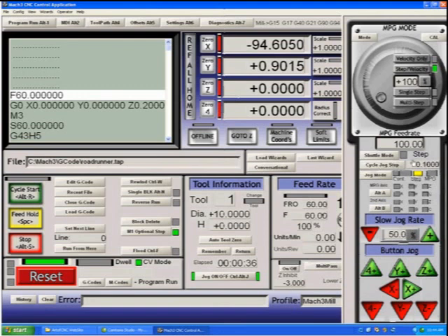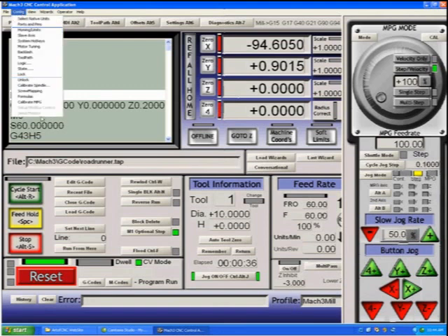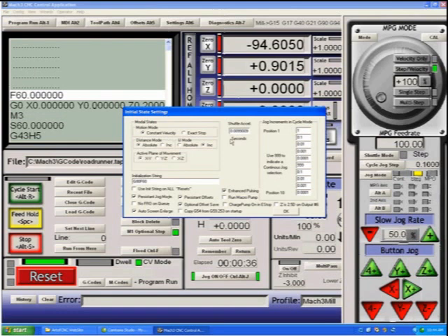And you can set these cycle jog steps in the configure state menu. Here are the ones that we are cycling through when we press this cycle jog step button. You'll see an entry here, 999. 999 triggers the system to switch back to continuous jog. It's a way to get back to continuous jog just by cycling through.